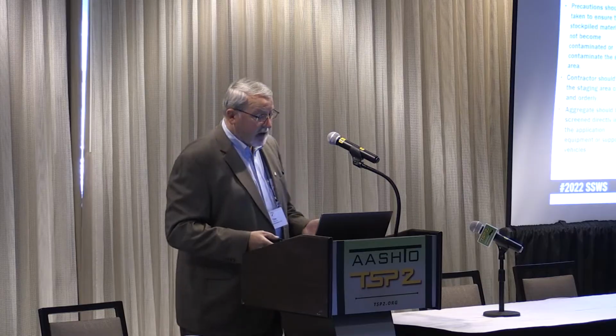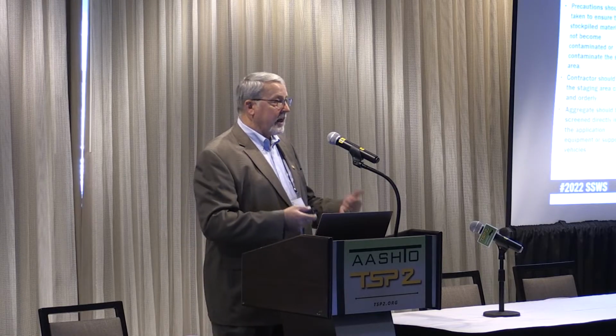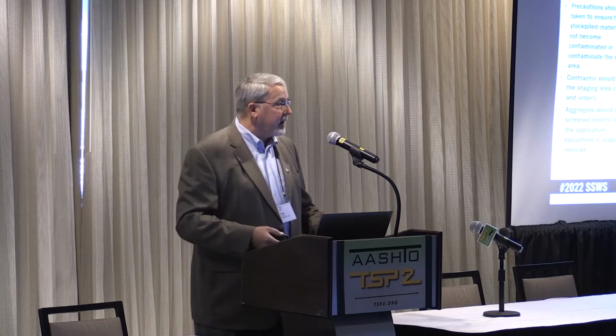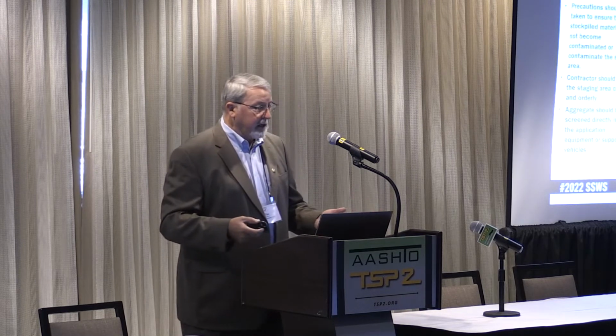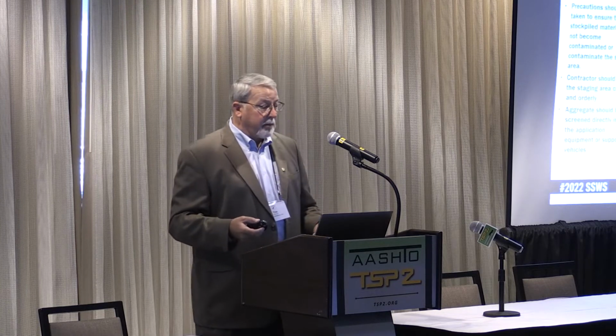Screening of aggregates. I don't think it's a huge issue out here. Out west, they do have a lot of dust abatement issues, and screening of aggregates is by permit only. They don't like the dust. Not typically an issue for us in the south. We've got high humidity. Moisture contents in our screenings are generally anywhere from 3 to 5%. So dust is typically not a problem.